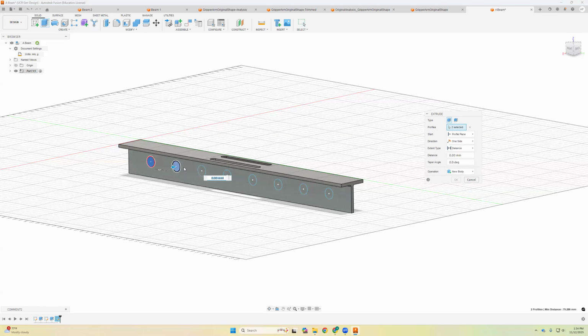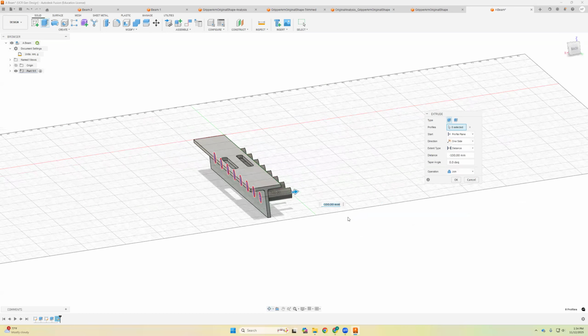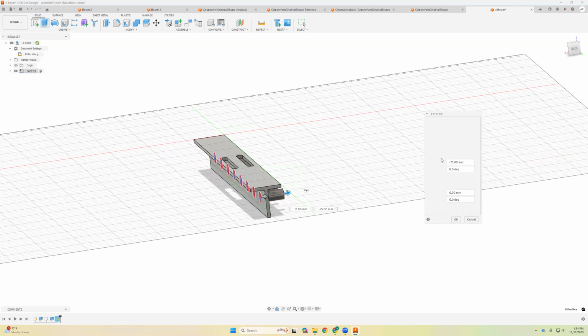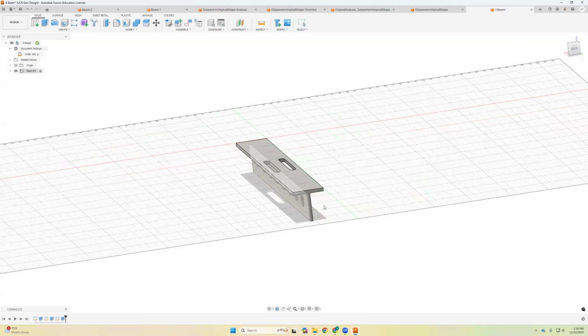Now I'm going to select all these profiles that we just created and use these two arrows to do the cut. You see here it is -100, and here is cut. If again I select join, I'm adding something. You can either add to the left, to the right, or turn on both sides, which means you have control for two sides. But in our case, one side, so let's just select cut and done.